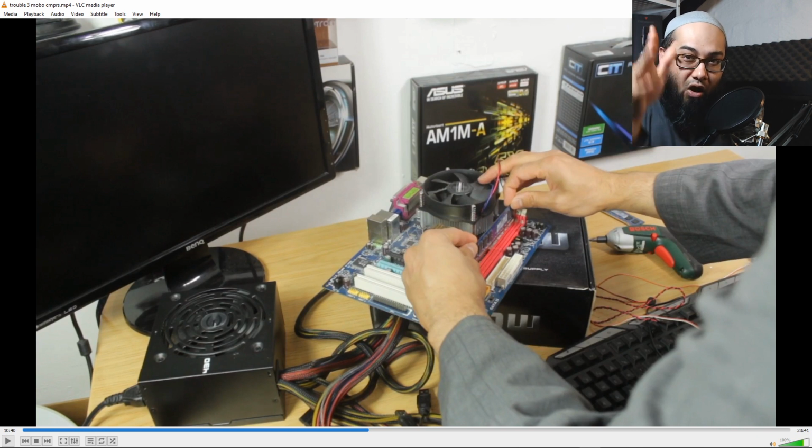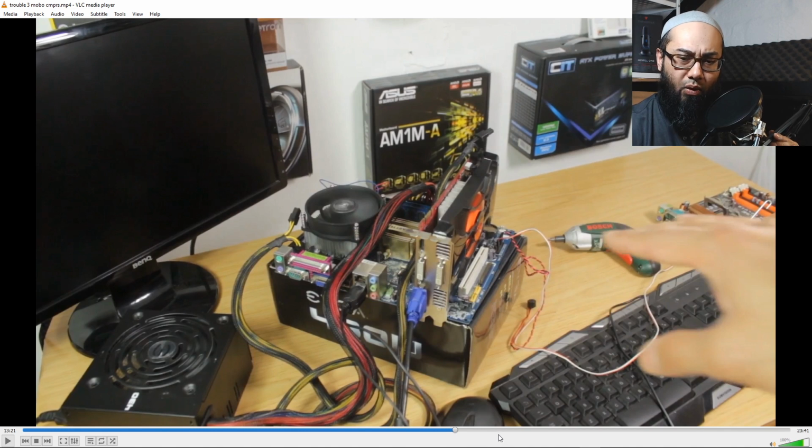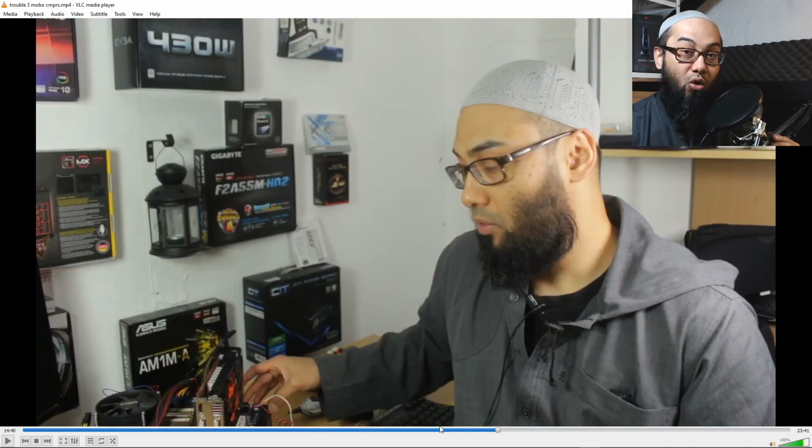In that case, because this motherboard was a dead motherboard, we waited for a POST in a live uncut video, and no POST was ever given because it's a dead motherboard. And what I mentioned in there was that when you do this test, never make assumptions. On, I think, one of the motherboards, the second one, there were no LED lights.